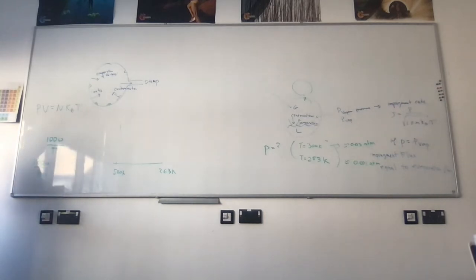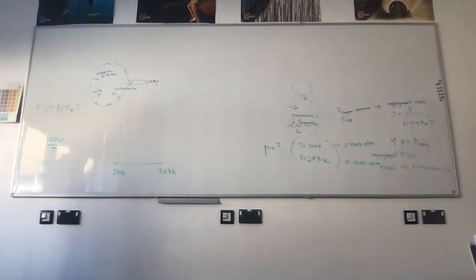So vapor pressure is all about stability, and we could see that it ranges. Some of these guys are better, some of these guys are worse, but all of them have vapor pressure which is not negligible. Which means that you need to supply the material in gas form if you want to stabilize it, which is bad news for vacuum. Okay, does that make sense? The higher the vapor pressure, the worse it is for vacuum, especially if you heat these guys up.